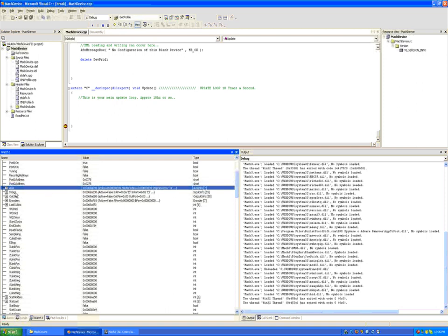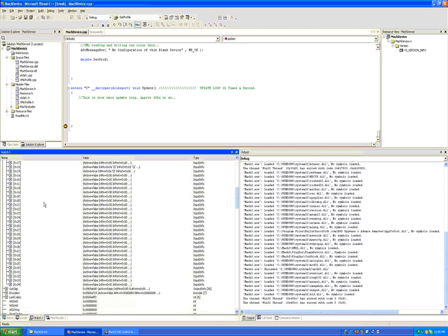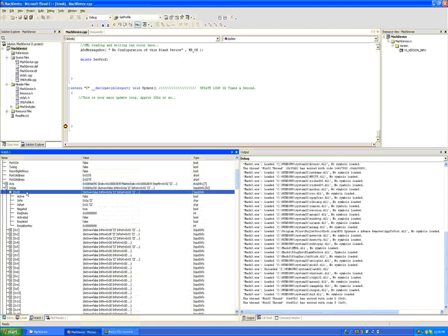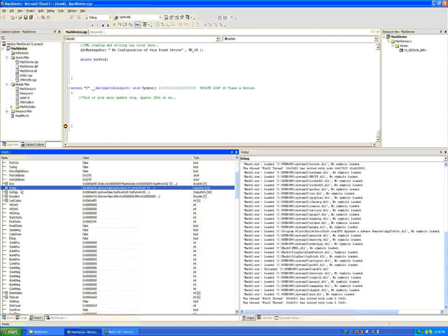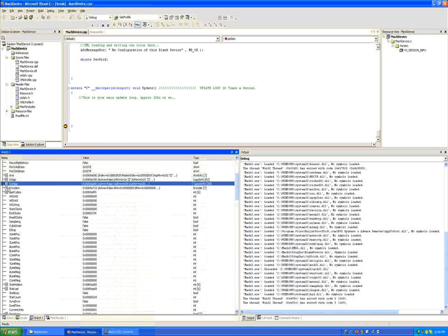You can see we have a variable in the engine called insigs. Insigs is a list of all the input pins. You can see that there are hex 34 of them, and for each input, for example input 1, we can tell whether it's false, what pin it is, what port it is, whether it's negated, its required state, whether it's activated, whether it's emulated, and what its emulation key is. So there's a structure for each input signal, and there's a corresponding structure for each output signal.